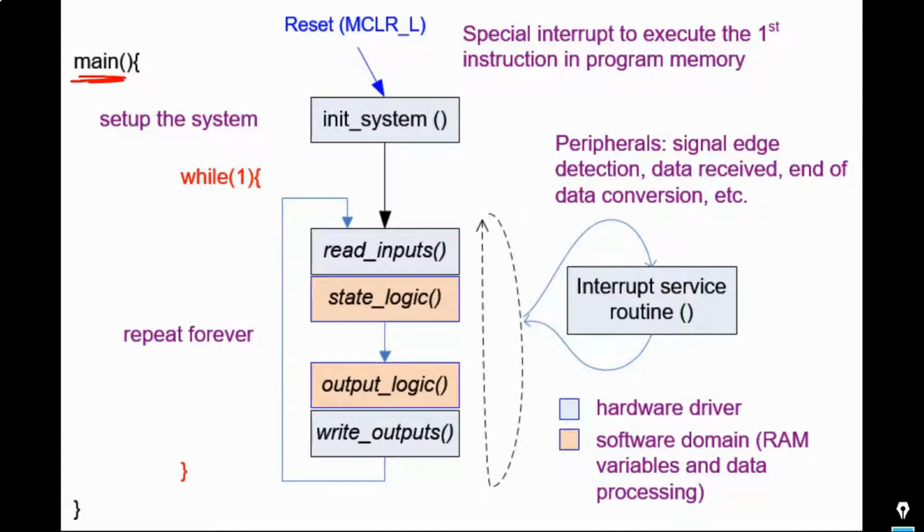So to start, there is the reset signal, naturally, the master clear that they call it. So when you apply the power supply and when you click the button master clear, this is nothing but what we know as clear direct. Asynchronously, anytime that you click that signal, the microcontroller starts again executing the first instruction in the program memory.